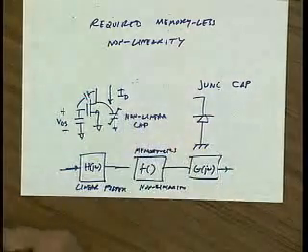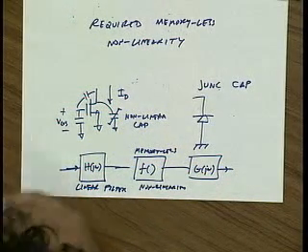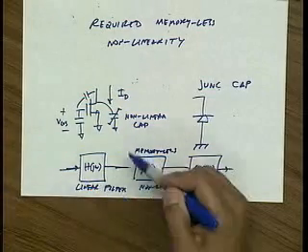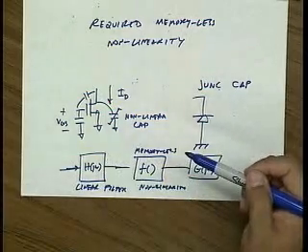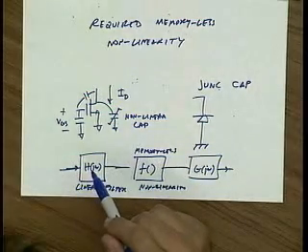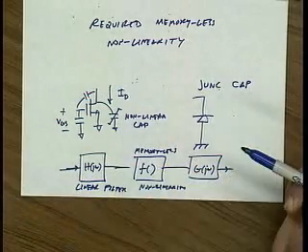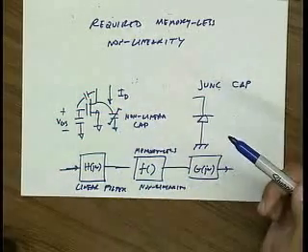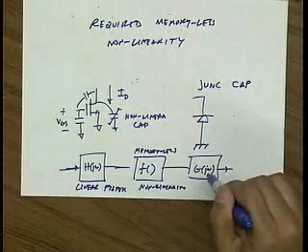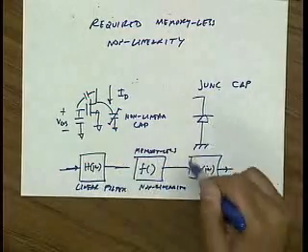Okay. So it seems like the techniques that we've developed, if we ignore this nonlinear capacitor, can still be applied to even a circuit that has frequency dependence. And in particular, if you're careful, you can just do this by inspection. So for instance, if you have a tuned amplifier, then you know which distortion products are going to get filtered and which ones are not. So if I come in with a two-tone and apply it to some memoryless nonlinearity, the output will have third harmonic, fifth harmonic, second harmonic, all the intermodulation products. Well, the harmonics will get attenuated by this filter. The intermodulation terms, the ones that fall in band, into the pass band of the amplifier, will not. Let me just draw a picture for that.